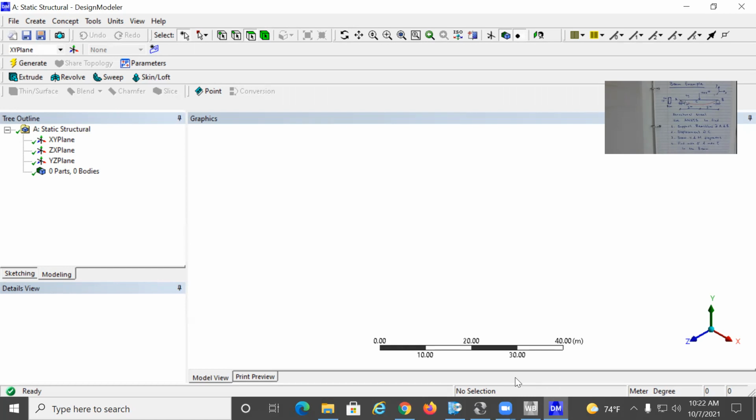This beam is prismatic. So even though I have 2 line bodies, they get the same section. So I don't have to create 2 line bodies. I can make it 1 line body by just adding material instead of add frozen. When you solved your homework problem, you had to use add frozen. But for this example, I can simply use add material, as we're going to see.